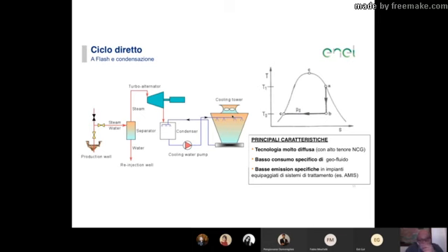And by doing this, in emission, you don't have much H2S. However, by dissolving the SO2 into the geothermal fluid, you displace the calcium carbonate and you form calcium sulfate, and you produce more CO2.